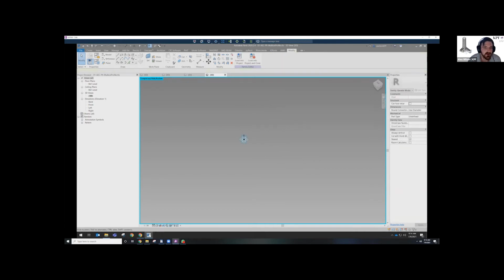If you have a point that you need to offset, so for example, if I jump all the way back to here, which is the completed example, if I wanted to create a parameter to offset from the face of glass, so the mullion sits behind the face of glass in this instance, the easiest way to do that, or the most stable way, is by creating a point, snapping that point to the adaptive point, and at that time, you can start to drag that point off. Wait, I don't have 3D snapping turned on. My bad.